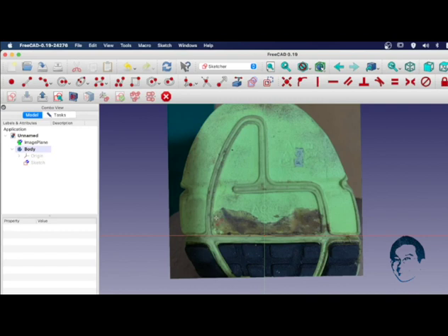Select the line tool here to draw the line from here over to here. Next, select the arc tool to connect them. Make sure that they are connected here, and move to this point. There you are, get the arc right. Okay, and continue the arc since this is also an arc itself. Alright, get it right and continue it to this point.